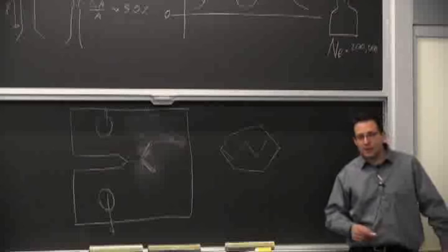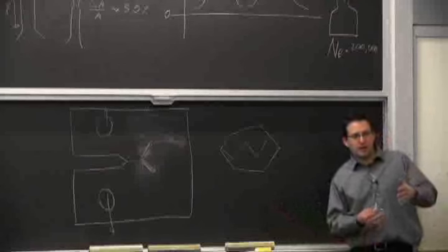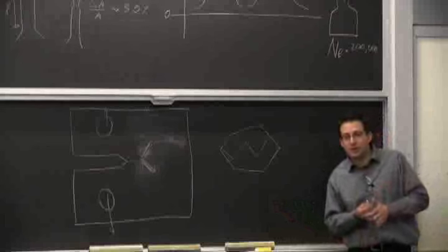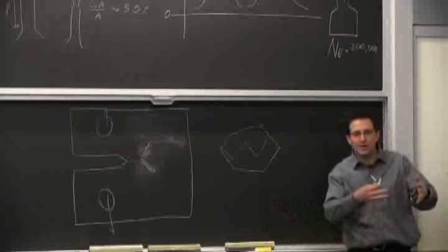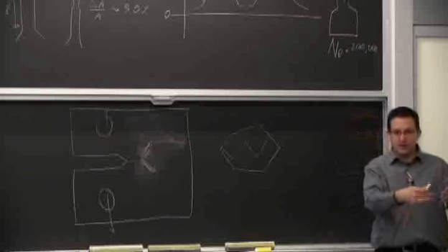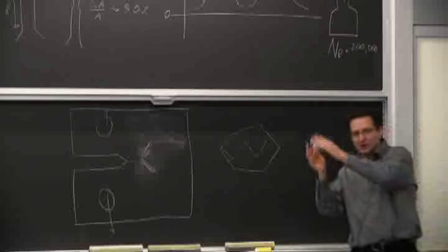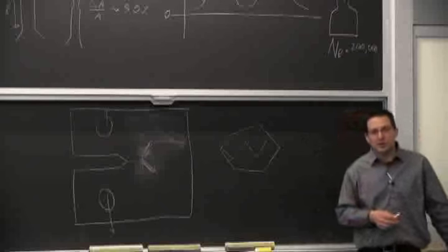Because if it turns out you got a big grain that's oriented in a way that's hard to start shearing, then for a little while you have more resistance. So your crack growth rate is going to be less to enter that grain. And then you go through these little tiny grains that are just going to go faster among those.